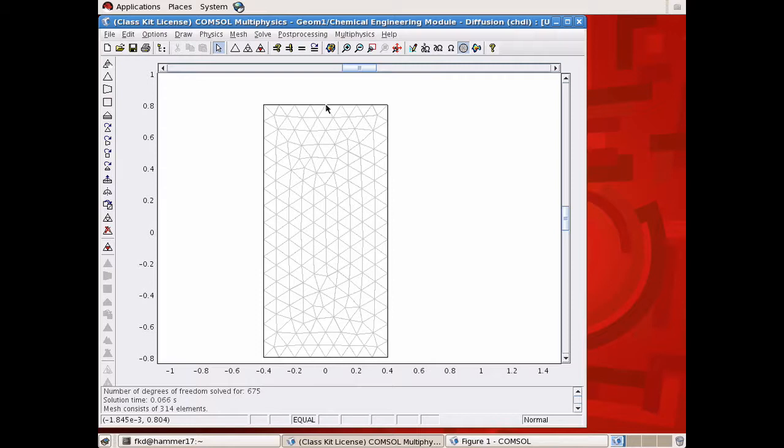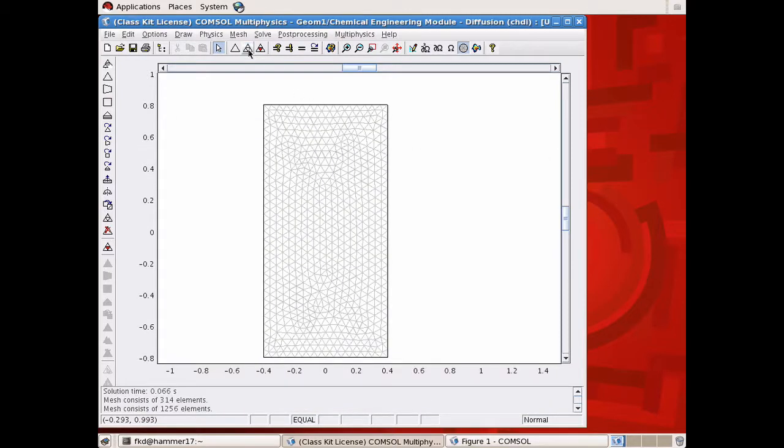It's because it's automatically meshing and it uses some algorithm to do it. You can prescribe it so that it actually has a regular rectangular grid. And in some cases, for instance where you want to reference how the material properties change at a point, you might want it to be exactly a regular grid. No, I guess the real question is, is this an improvement on gridding techniques? This is a coarse mesh, so I'm not exactly sure. Certainly you can make the mesh finer by refining it.